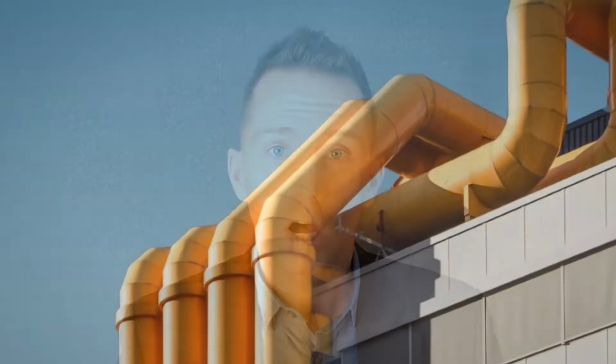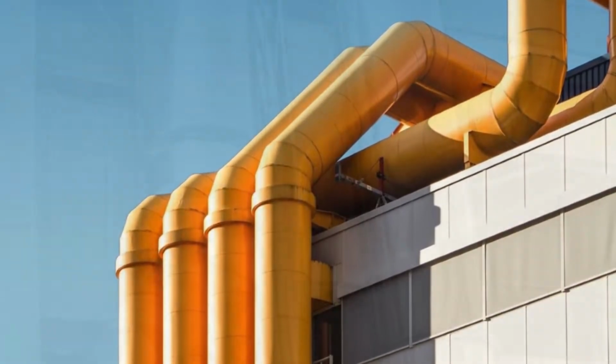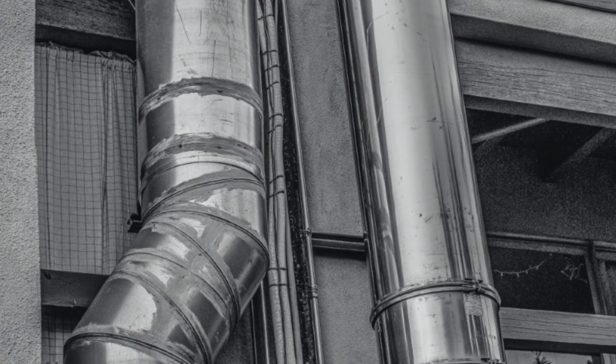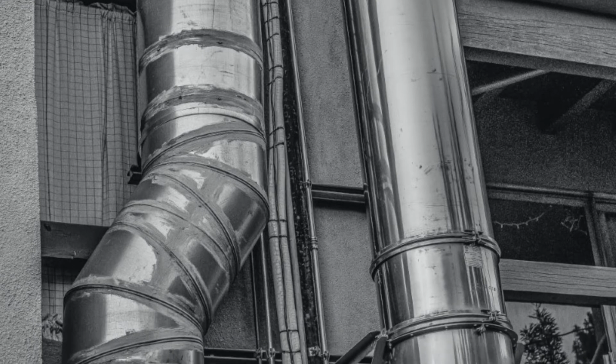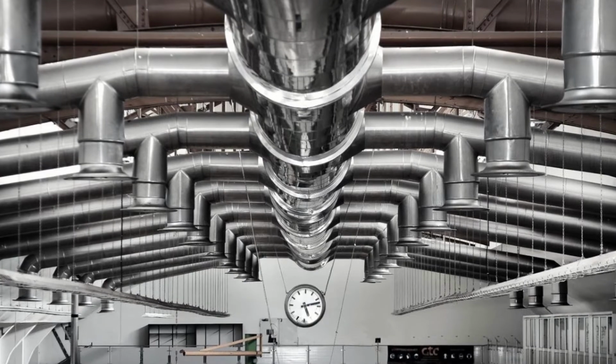Okay, number 5, plan the ventilation system. Chances are you're not a heating ventilation specialist, but if the sub-trade, the builder, plans out that system ahead of time as the building is designed, you end up with a much more efficient system, better performing system. The cost of the ducts comes down, but most importantly, the cost of the equipment that pushes the air around. And that equipment is not cheap.